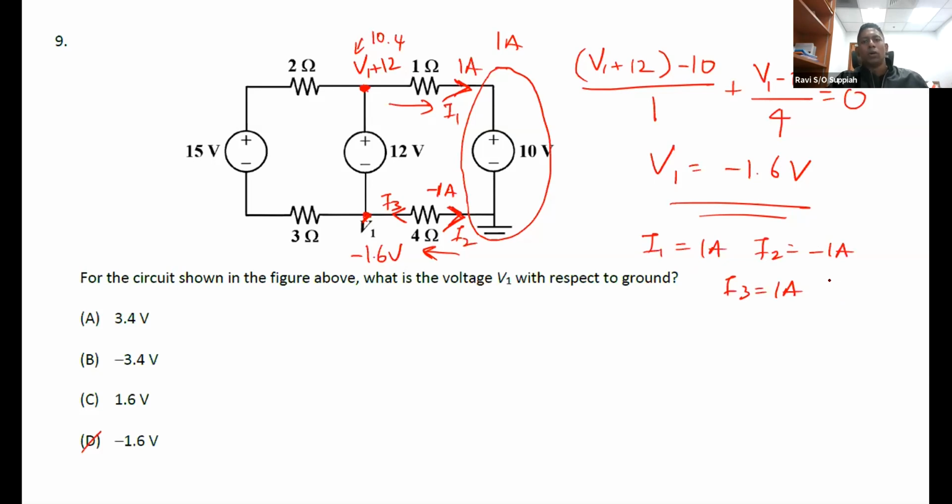Okay, so you can stick with the original assumption of your directions, and then your plus and minus will be following that original assumption. Or you can make a new assignment to reflect what you have just learned. Okay, what is the actual current flow now? So it is just a convention based on whether you make the initial assumption or you make the final conclusion with the values that you've already calculated. Okay, so that is how you get your plus and minus.